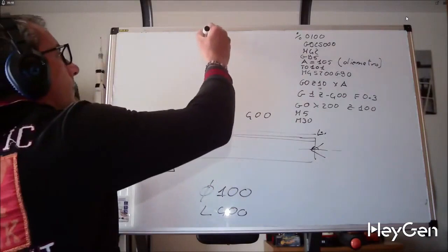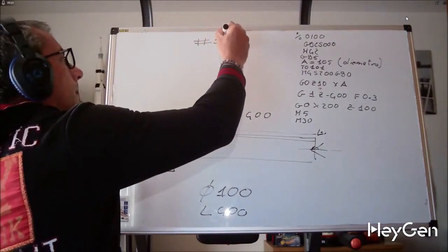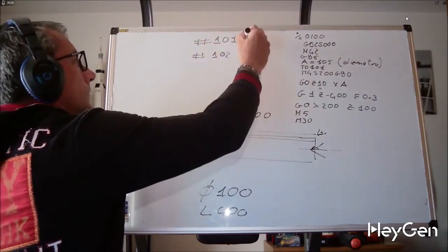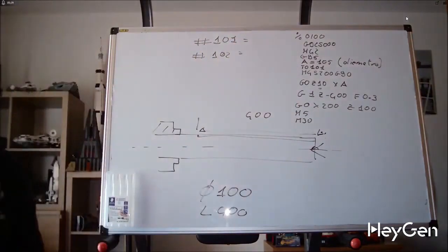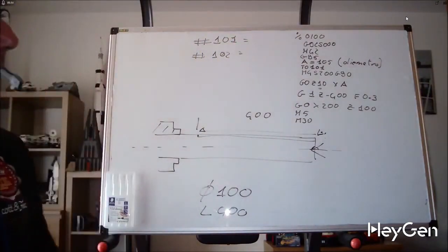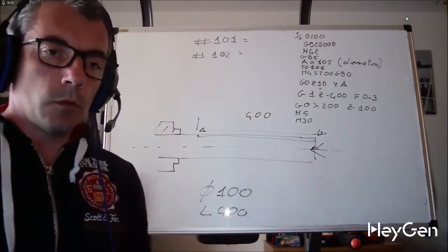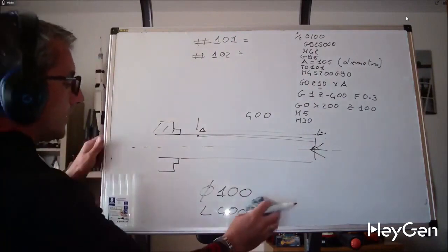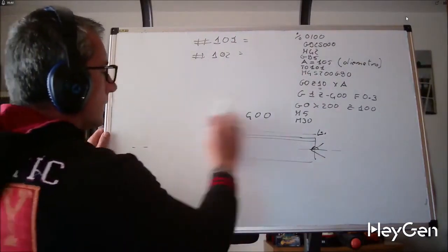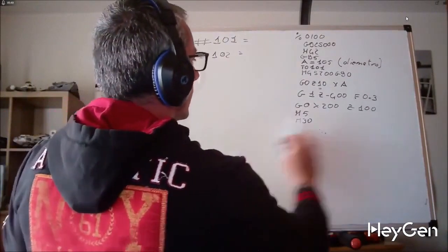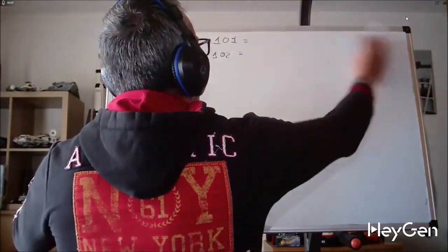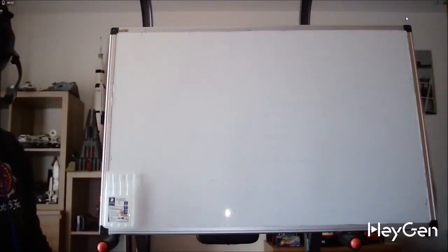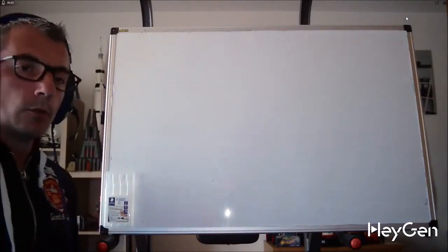For example, Fanuc indicates variables as hashtag 101, hashtag 102, and so forth, and then you match them to numerical values, and our program takes on different characteristics based on the variables I put in the program text or modify during the program execution. For the sake of convenience, we'll just refer to the variables as letters.